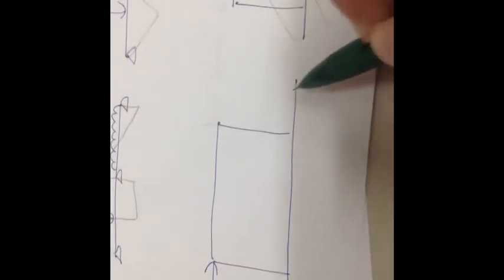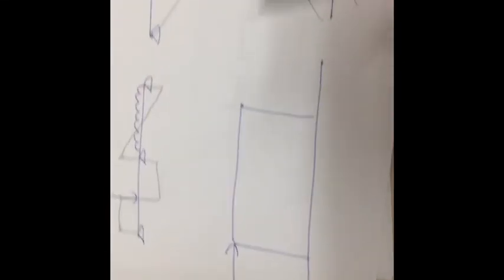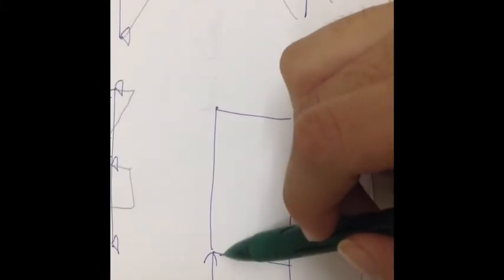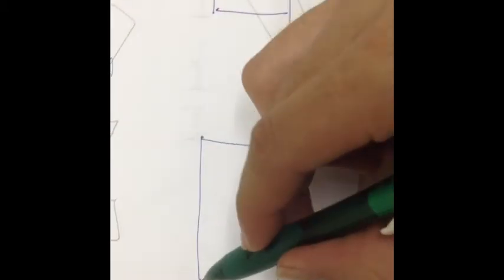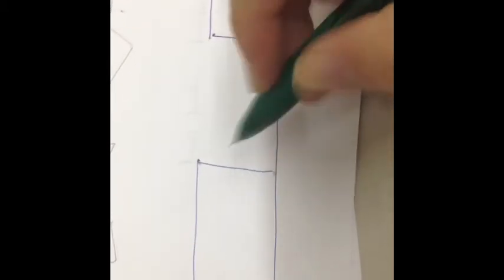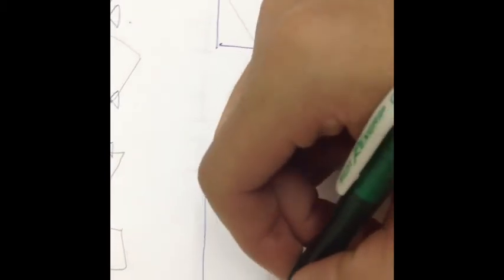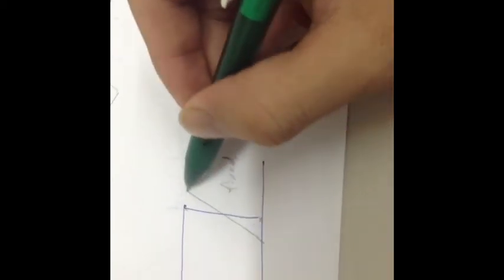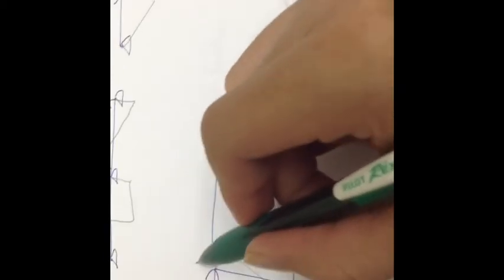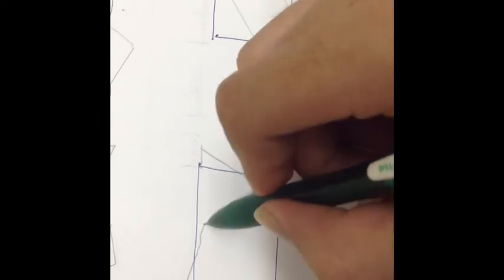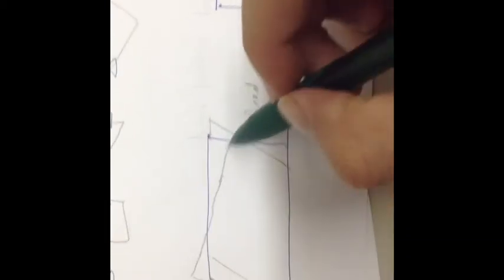And this is the frame. That's quite hard to draw for me, and I wish to impart this kind of knowledge to you too. There's a force pulling at the side, so you can know this is fixed, this is fixed, this is fixed, this is fixed. They are all fixed. When the force is pushing like this, you have a moment here, and because it's fixed, there's a moment here. This applies to both sides, and on top here you also have a bending moment. Okay, so it should be triangular.